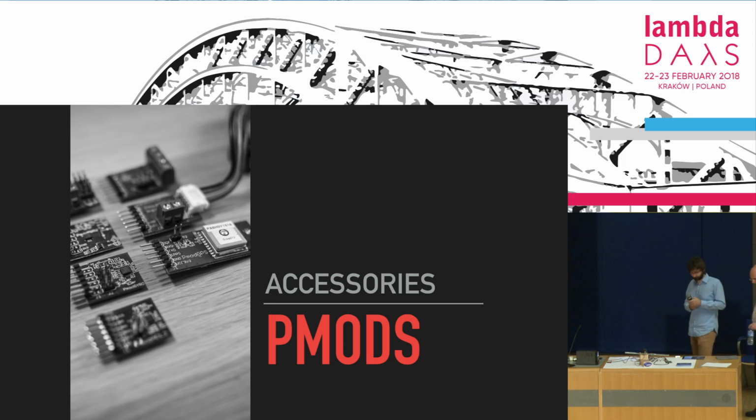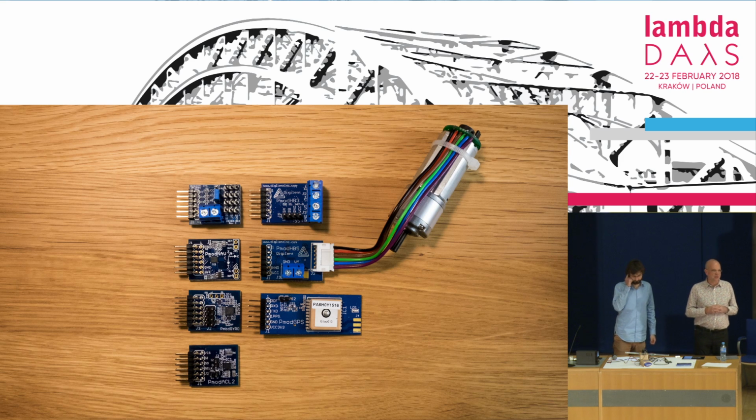So I think the Pmods are my thing. The connectors you saw before actually conform to a standard by Digilent. It's called Pmod. And you get lots, meaning over 100 different sensor and actuator boards, quite cheaply, and you can just plug them into these Pmod ports. There are different kinds of Pmods. That's the different SPI, UART, GPIO interfaces. We are actually providing drivers on the Erlang level for lots of the most usual Pmods. This means that basically you can build all kinds of things with the board. You're not limited by the board. You just plug in the Pmods that you need, and then you can build almost arbitrary things.